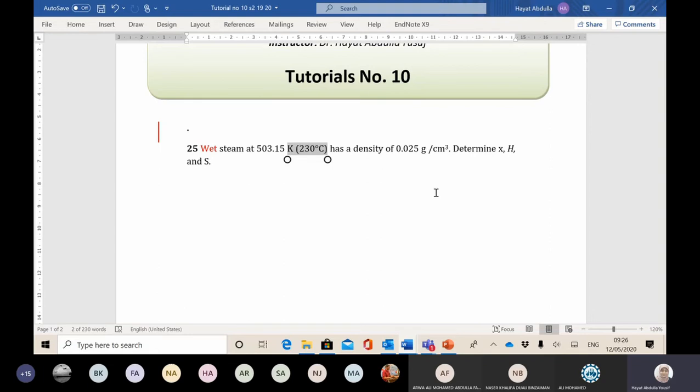So what we have here is the actual specific volume. From the thermodynamic tables, I have the V liquid and V vapor. And in this case, I can apply the saturated mixture equation, which says the property M is equal to X liquid M liquid plus X vapor M vapor. The quality X, whenever they write X here, simply means the mass fraction of vapor.